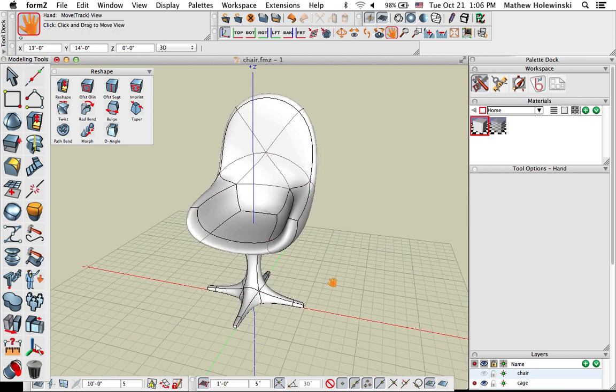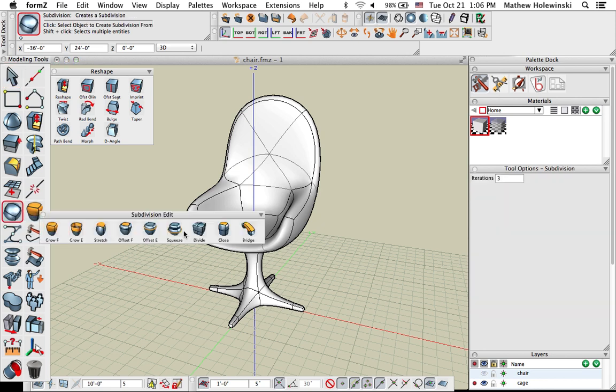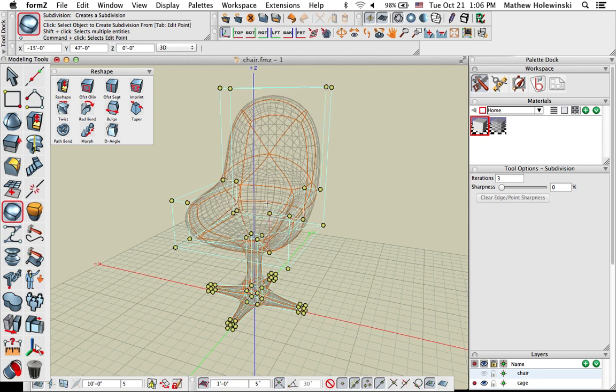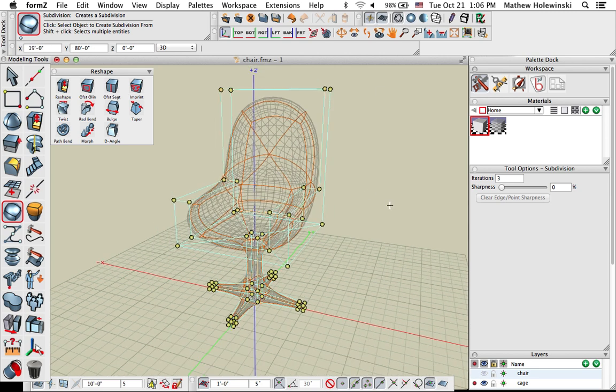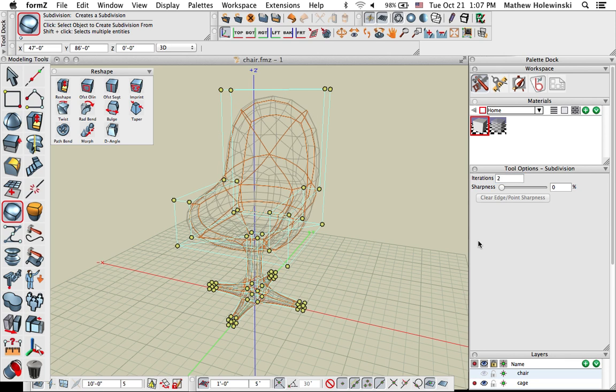We're ready for the 3D printing process, and so we have to decide the meshing resolution that we're going to assign. Now, when we have the Subdivision tool active, and we click on that object, you can see that there's this number of iterations, and that will determine the resolution of the quad mesh that's assigned to that subdivided object. If I were to select this as being 1, then you can see we have a coarse polygon object. We select number of iterations 2, it subdivides it even further, and 3, and so on and so forth.